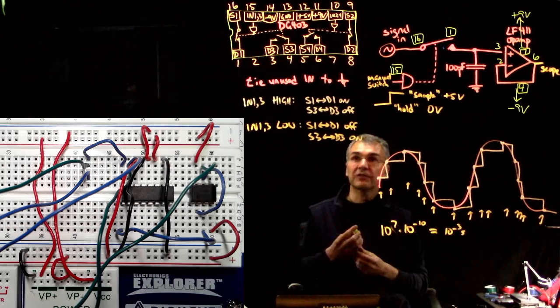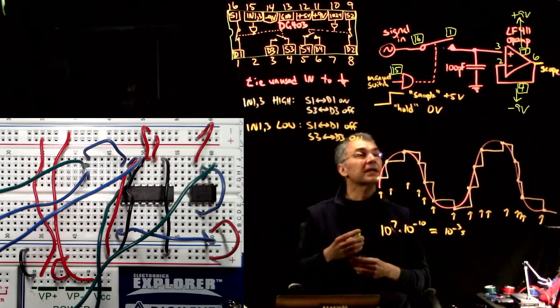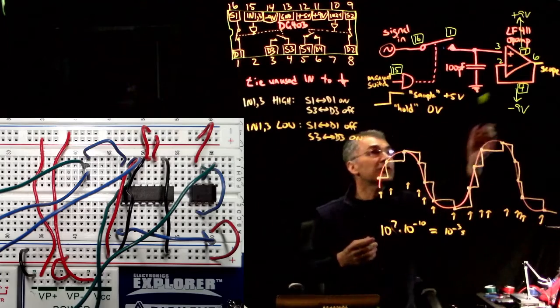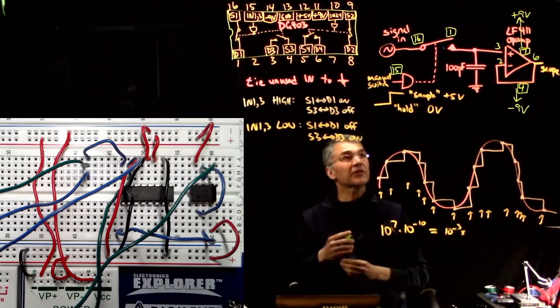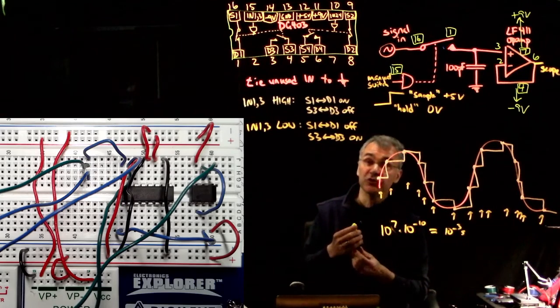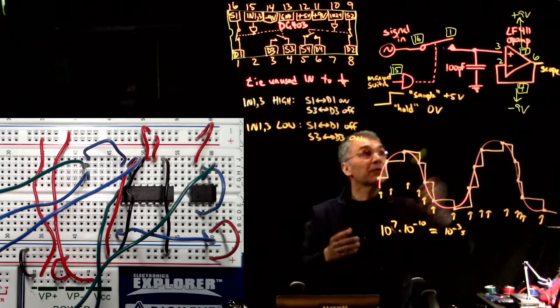This 411 has a really tiny, think like picoamps or tens of picoamps, bias current. So then you can look over here with the scope probe without perturbing the charge in the capacitor over here. So that's pretty neat. So I see this is actually a really useful use for a follower. You want to be able to look at a signal with a scope probe without affecting it.